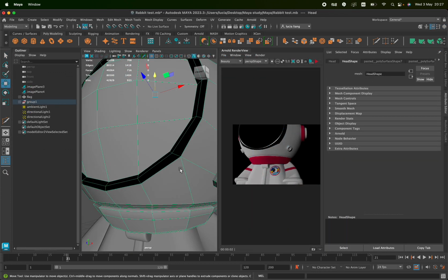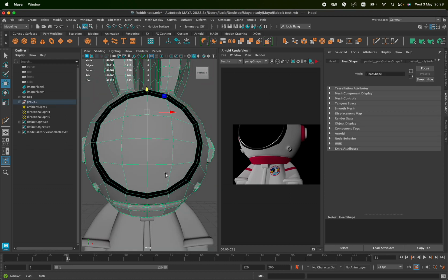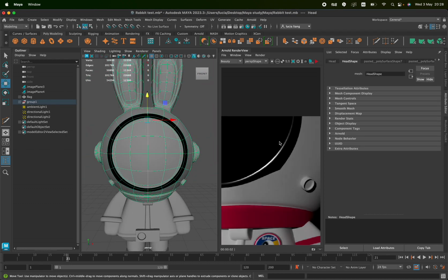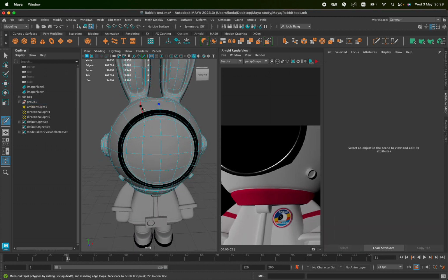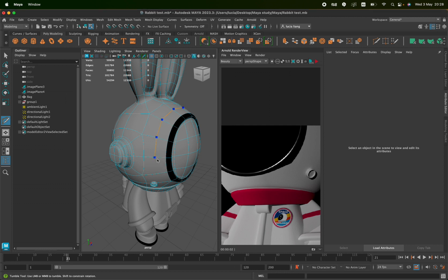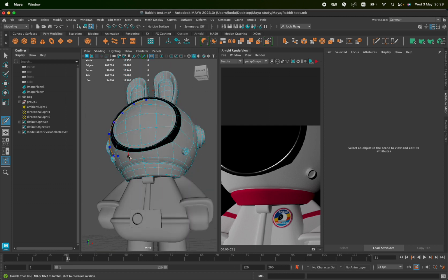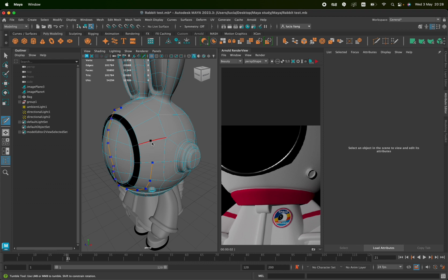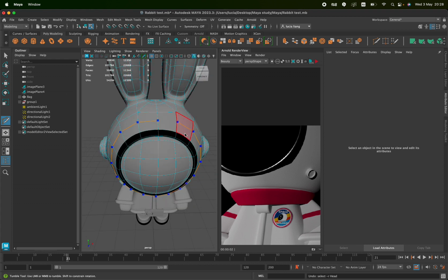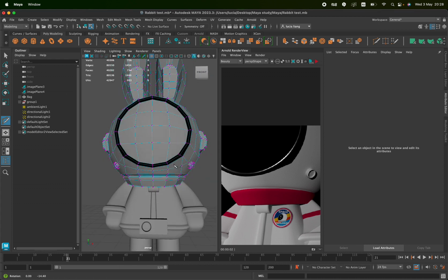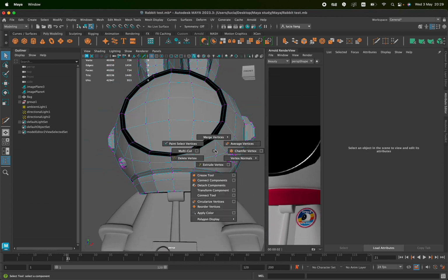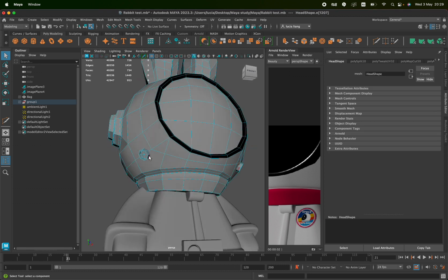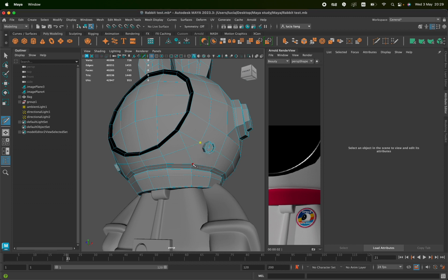Here I also found a problem, which is that the rabbit face has a strange place like this. It needs to be modified. The ring is not flat. The way I modified it was to add a line using the cut tool, and then delete the extra lines, keeping all the faces in 4 sides to make the lines more even. Because it is better not to connect 5 lines to one vertex.